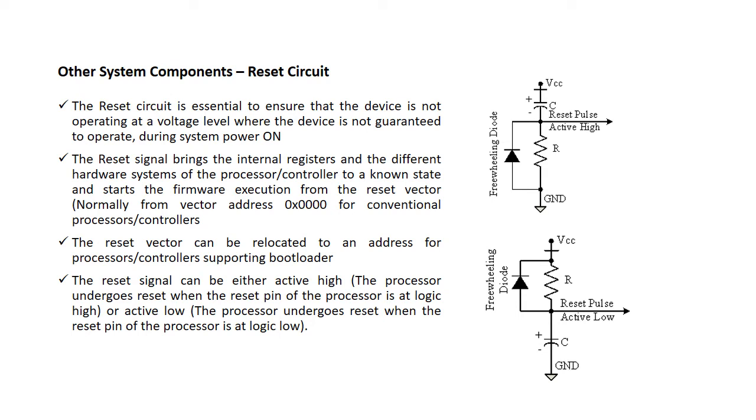When the reset exception occurs, the interrupt service routine which should execute in response to it will be executed, and the starting address of this reset interrupt service routine will be placed at the very first location of the program memory, that is at 0000, whatever may be the number of bits per address. Okay, the 0th location of the program memory will be for the reset vector.